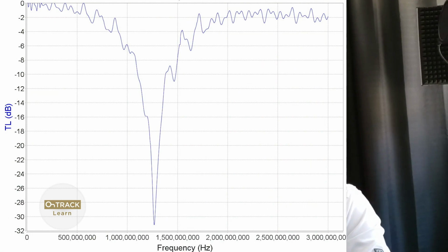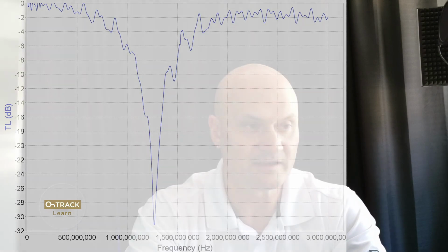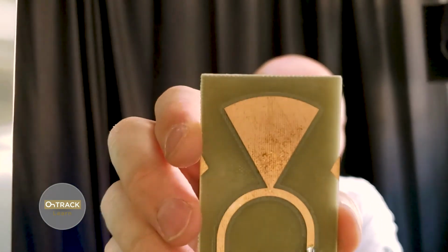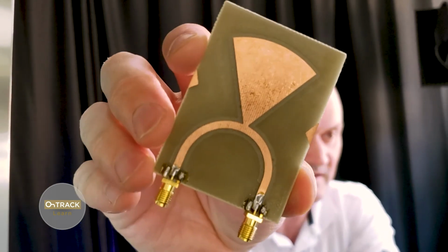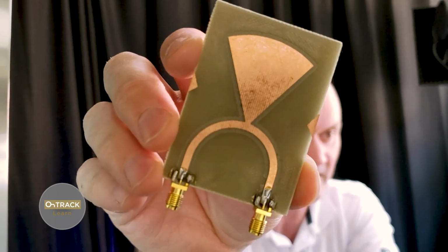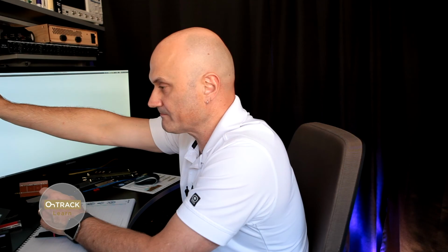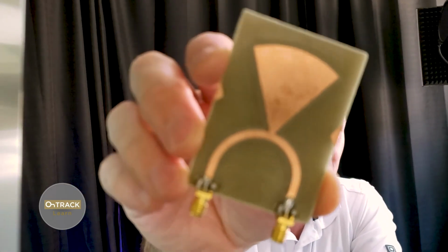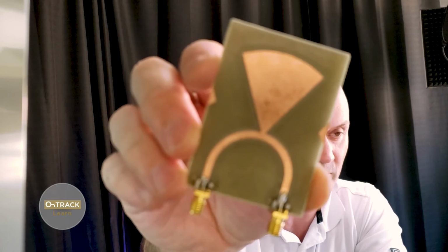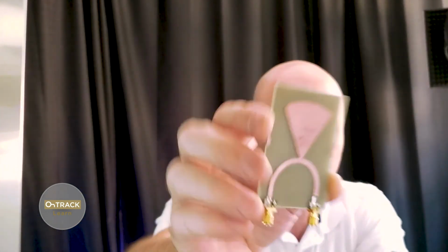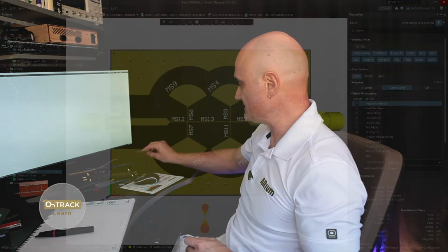And of course we can broaden the notch and make it a broader frequency response by adding capacitance, and one way to do that is to use a radial stub. You'll see these really commonly used in RF and microwave boards for matching networks and filtering networks, as bow ties. Maybe to shrink the size, instead of one big one on one side of the transmission line, you might put two smaller ones on each side. But this is like a huge capacitor.